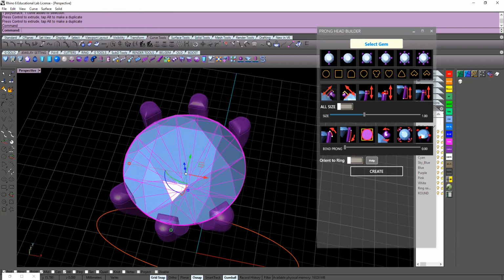When it comes to your prong sizes, when you're designing in CAD, you can make them any size you want. So it really depends on how big the stone is. Anywhere between 0.8 and 1.2 millimeters is pretty standard. Though occasionally you need to go beyond that.